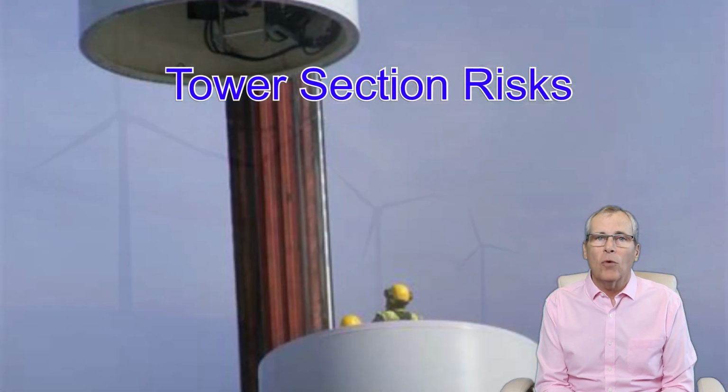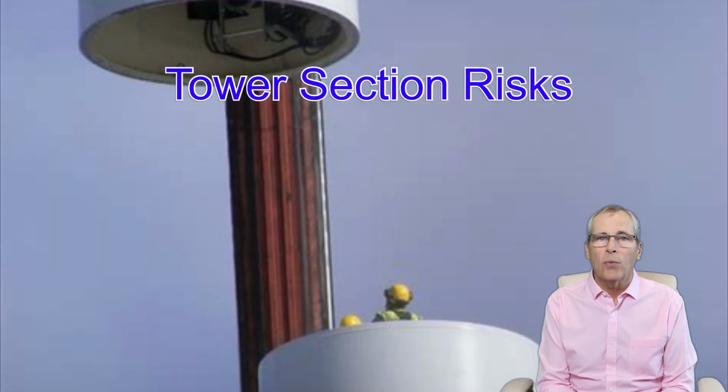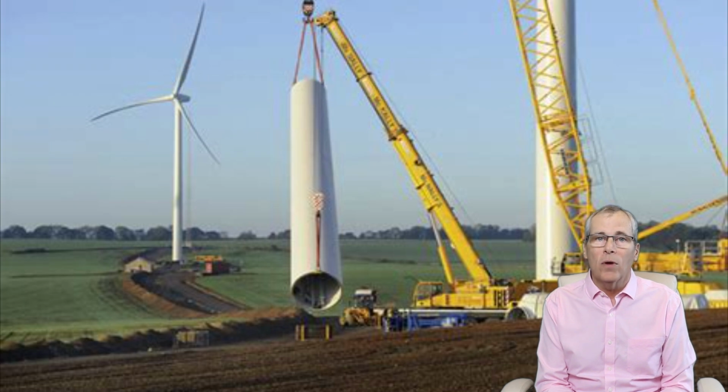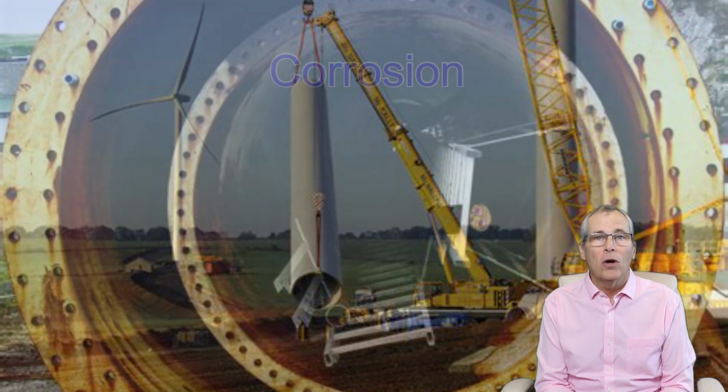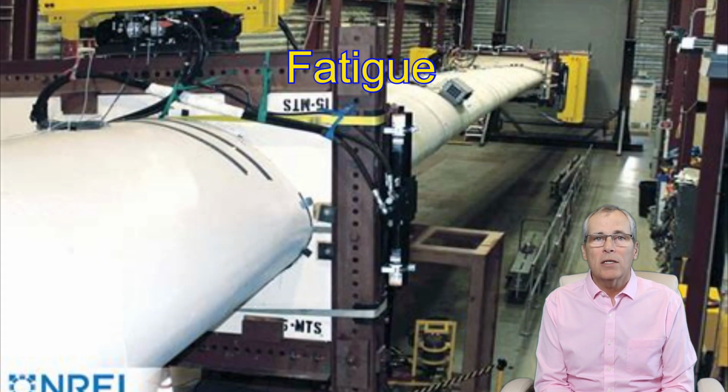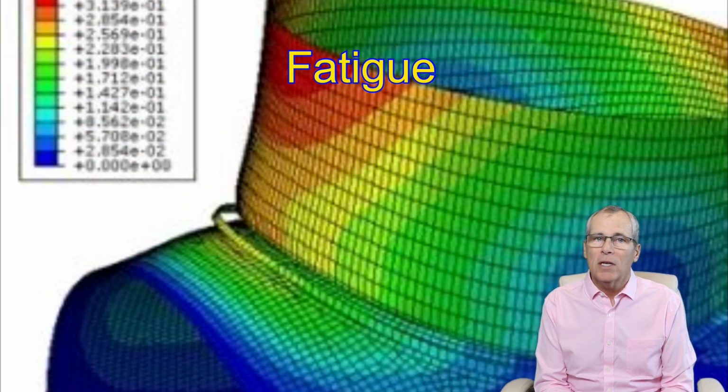The tower sections of a wind turbine are critical components that support the weight of the turbine and keep it upright. There are several risks associated with the tower sections, including corrosion. The tower sections are exposed to the elements, and over time they can become corroded, which can weaken the structural integrity of the tower and lead to failure. Fatigue. The tower sections are subject to constant stress from the wind and the weight of the turbine, which can lead to fatigue and eventual failure.